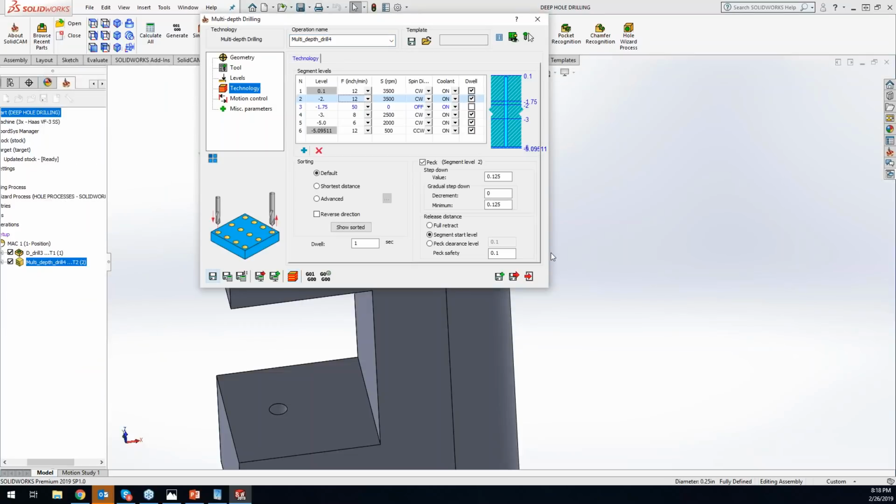So like I said, it's a completely customized cycle for whatever your manufacturer is recommending. And this has been asked by you guys, so we added it in here for you guys. And like I said, to really gear towards that custom drilling cycle. And you guys, you don't have to look at this as it's just for doing deep hole drilling. You guys can add this for, if you're just doing a 1-inch deep hole, and maybe that first, like Greg was saying, that first 1/4 inch, we need to speed it up and then slowly slow it down the deeper we get, kind of like with spade drills and stuff like that.